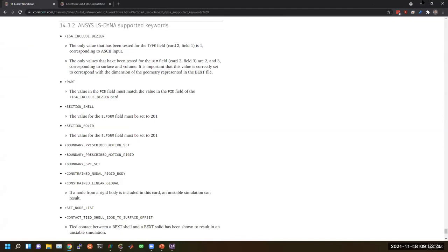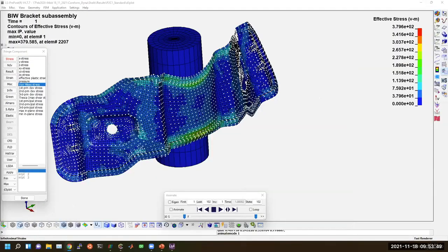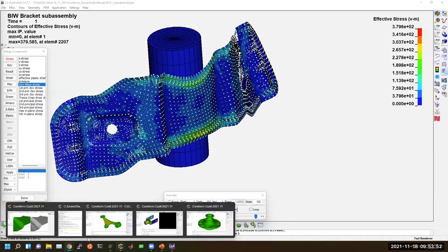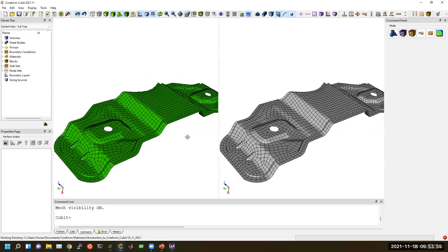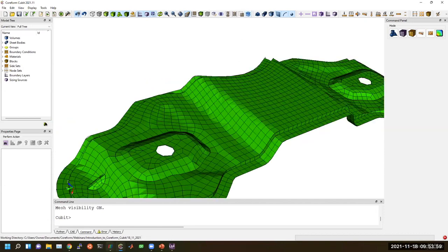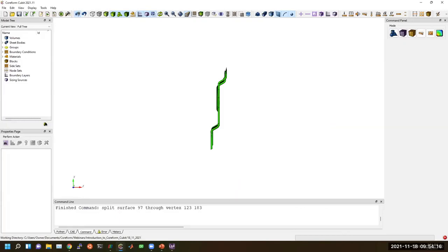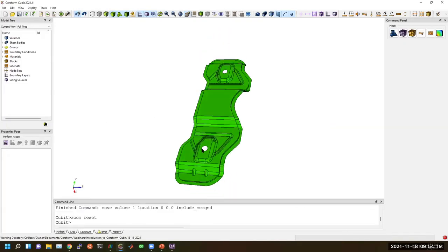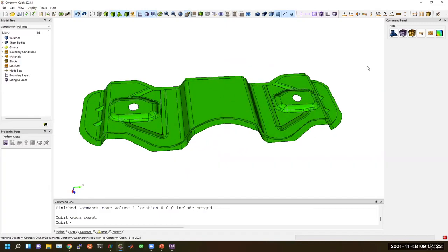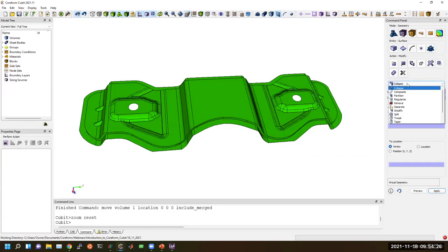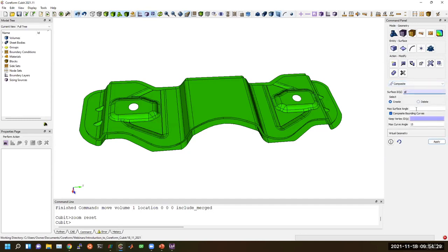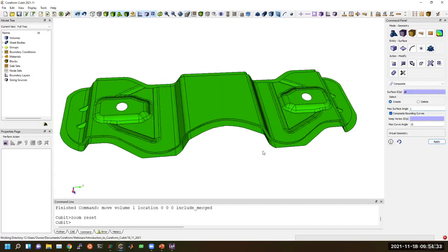Great. So another question, is it possible to decompose the whole piece without all of this process? I'm assuming that's referring to how we are setting up U-Spline models today. So one answer to that is Greg shared a webinar a few months ago showing the Flex IGA process, where we can get away with much less model prep. And that is, I think, one of the big benefits of IGA, being able to get away with far less model preparation. What we're showing today is a way of using existing traditional techniques to create U-Splines for inclusion in Coreform IGA and LS-DYNA. But absolutely, there are other ways that this can be done as well.